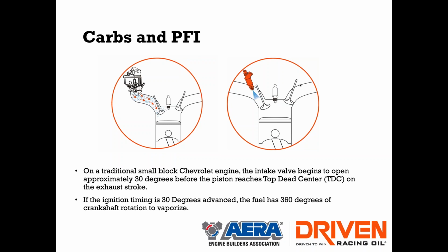And I want to make a good point here that atomization and vaporization are two different things. Atomization is the distribution of fine droplets of fuel in the airstream. You want droplets of fuel in the air, not big drops of fuel laying in the manifold or the intake runners.